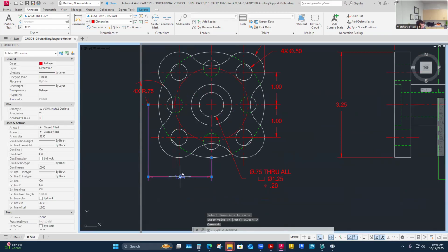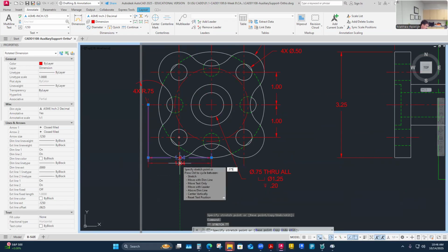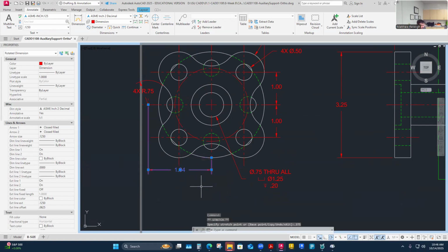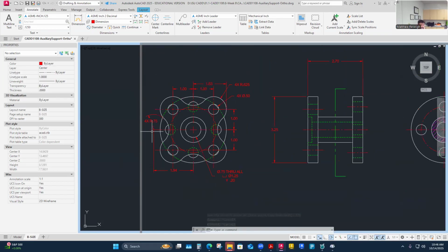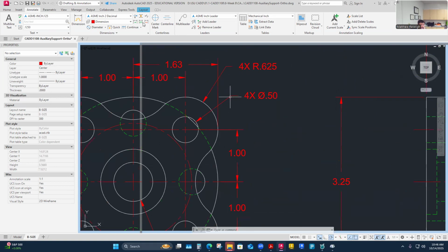This one I feel like I could space away a little better, like there. That doesn't look like that interferes. That's all right. I already kind of left that one. These I just need to cut through, right? So I'm going to cut this one with this one. So I'm going to cut the first one that's going to get cut with the one that's doing the cutting, like that. And that would be correct. Cut extension lines around dimension lines, and I consider this a dimension line.